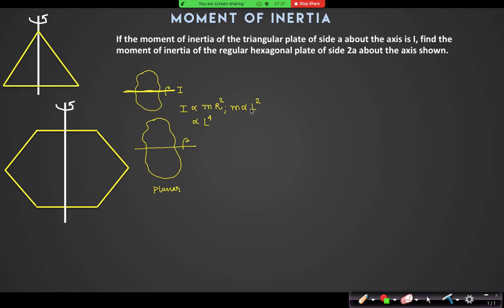So area becomes 4 times, L squared times, and r is also doubled, so there is another L squared. So length is raised to the power 4. I prime will be n power 4 I, if I make it n times. Yes or no?